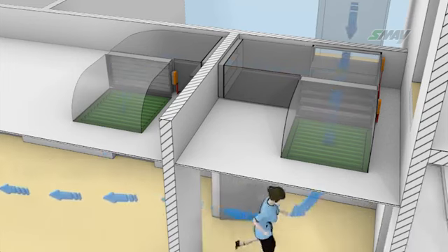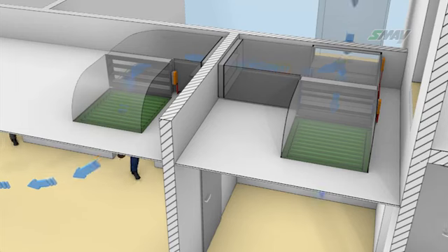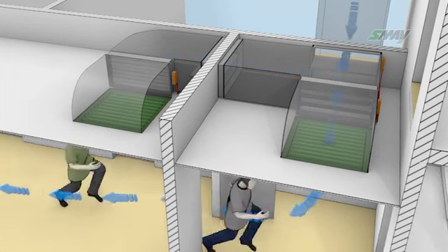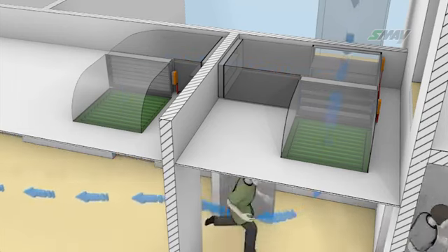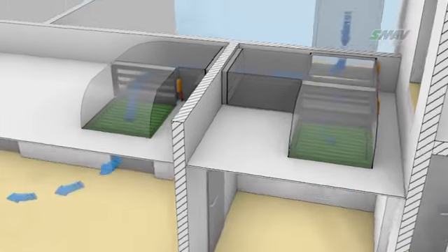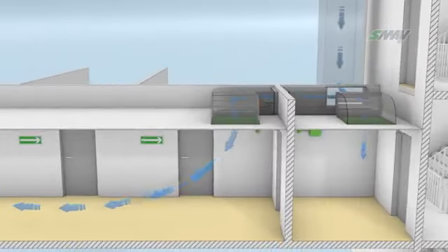Then, when the doors between the lobby and the corridor are closed again, pressure will rise in the lobby, which again acts as a control signal for the system, which begins to operate executing the pressure criterion.